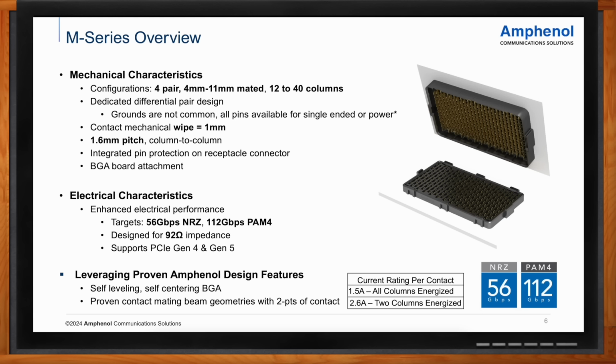We're 1.6 millimeters column to column. And the reason for that is for signaling purposes, and it also gives a routing channel that as a customer is laying out their PCB, they've got an area to route those pins out to their PCB.